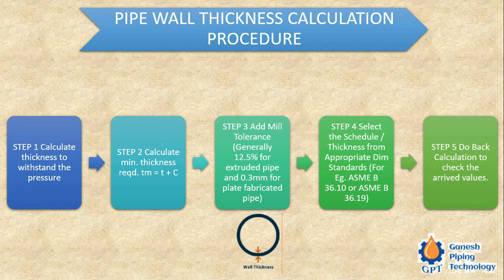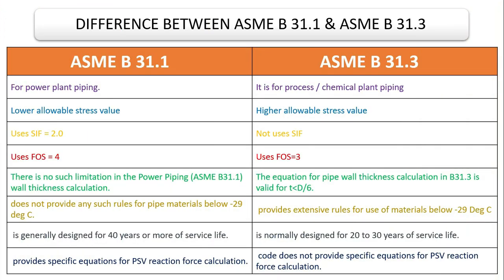So the second level will be the flange pressure. So first the flanges will fail, there will be leakage at the flange. So that is the flange pressure, and after that we have to design the system for the design pressure, which is lesser than that flange pressure. So this is the bottom line philosophy. So this is a comparative study.